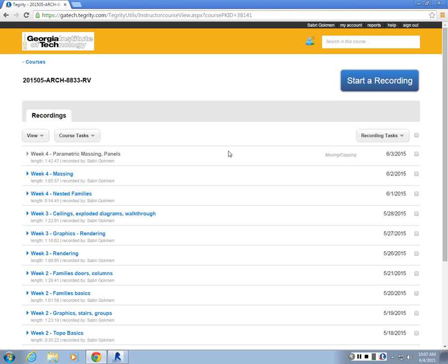Let's say something like this. And in the curtain wall panel family, we have 4 construction planes, right? Which is basically the side planes of the panel. And whatever you do here, it gets replicated to all these. So the module stretches basically, right?